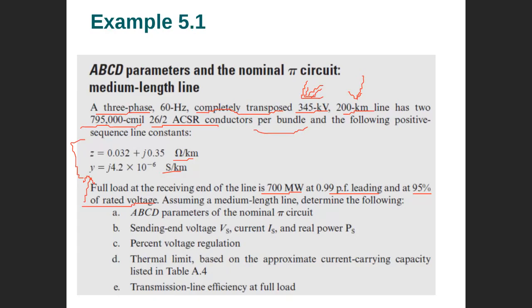And what is the load? This is the load power, real power, and this is the reactive power. This is the power factor leading. Therefore, you can determine the reactive power, and the reactive power will be negative. Why will it be negative? Because this is the load, and the load now is injecting reactive power into the system. How do we know? Because it's a leading power factor.